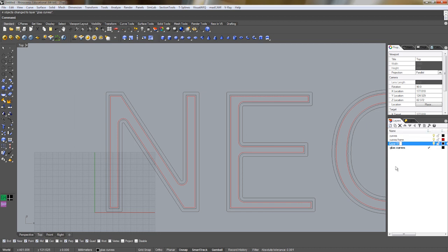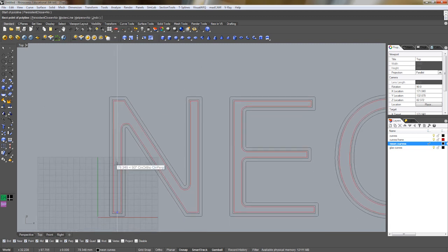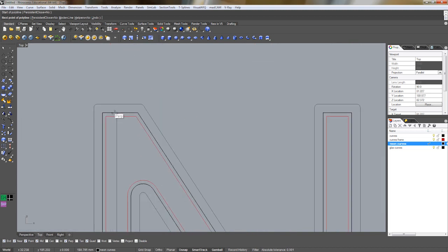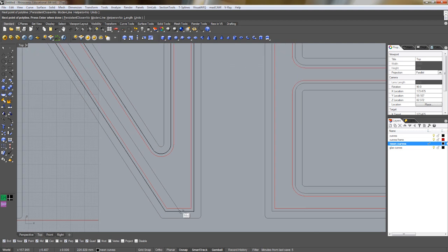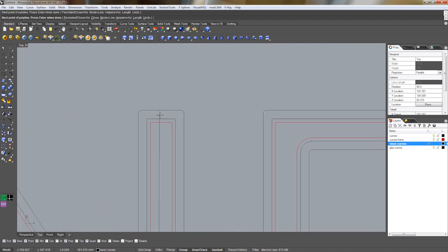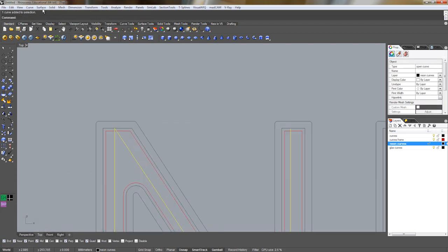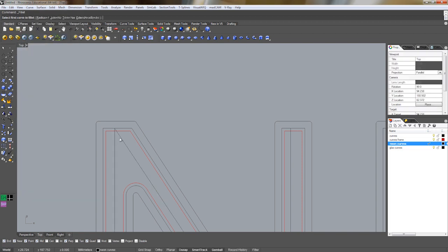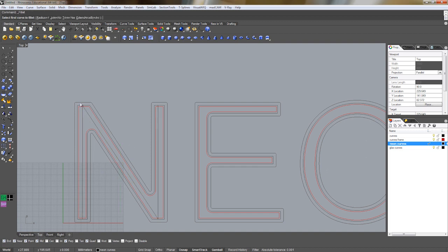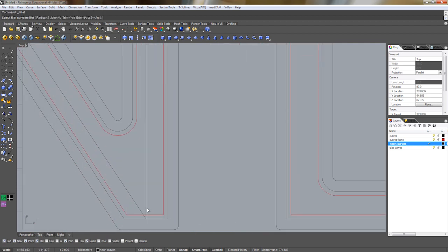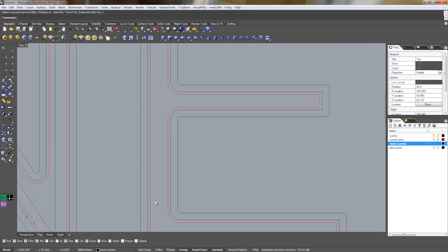We also gonna need curves for the neon light. So neon curves. Just gonna use these polylines here and snap it here. Of course, we need to fillet the edge here. Let's make it a bit more actually, because it's glass and you cannot bend glass that hard. Okay.